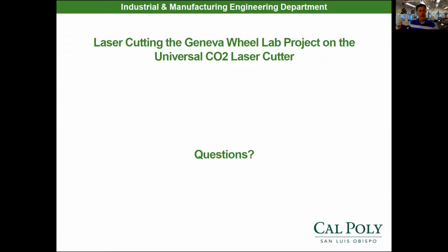Hopefully you've learned a lot about the non-traditional machining processes, at least 3 of them today, and why they're important. When we can't get it done with traditional, we go to non-traditional, which doesn't use shear stress. That's the key, right? They use other types of energy to remove material. Next week, we'll get into some of the other non-traditional machining processes like water jet. And then there's ultrasonic machining. It's how we can machine glass and ceramics. So there's some cool things coming up.